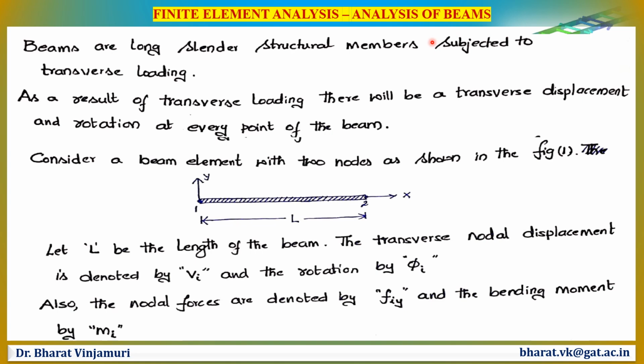The following notations will be used throughout the sessions. The transverse nodal displacement is denoted by vi, which will be in y direction, and the rotation or the slope will be denoted by phi i. Also, the shear forces will be denoted by Fiy, and the bending moments will be denoted by Mi.